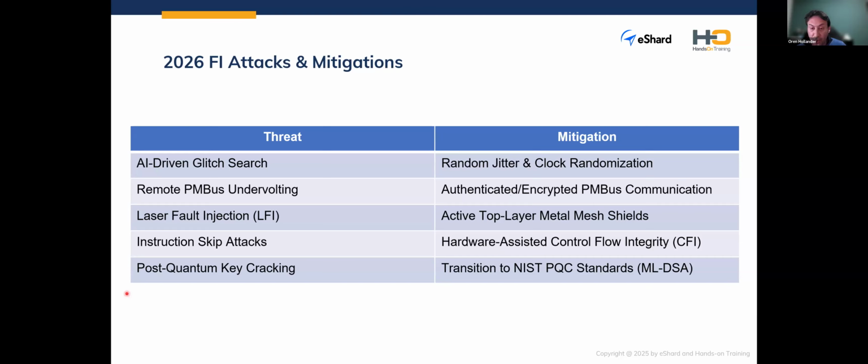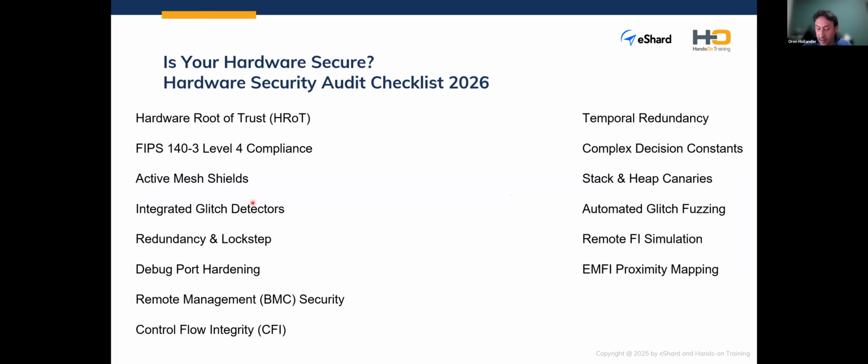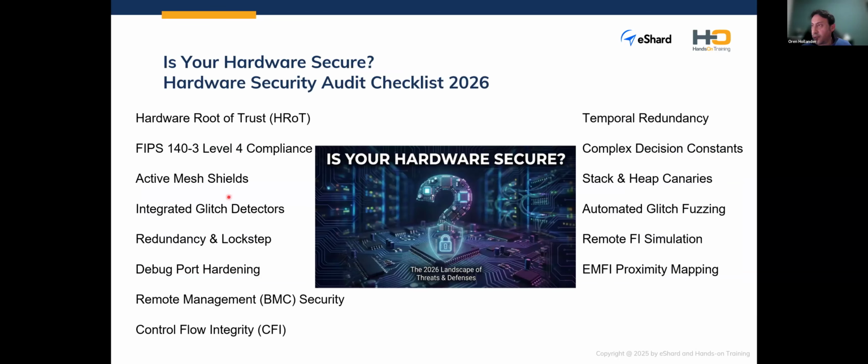So to fix it, you need to stick to the NIST PQC standards implemented within a secure enclave. That means you would like to run these algorithms in a completely isolated environment like NXP EdgeLock that I showed before, or Intel Secure Device Manager. The idea is that we would like to protect the mathematical operation from being glitched. We are not just protecting against the quantum computers of tomorrow, we are actually protecting the algorithms themselves from the hardware hackers of today.